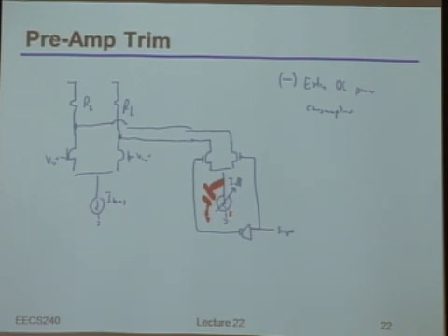Okay, so you said that I've already gained up the offset. It is true I've already gained up the offset. Now, if you think about it, the amount of current I have to spend in this thing is really proportional to this current. Right? Because that offset just goes through the GM of these input devices to become a differential current at the output. So if I want to cancel a certain amount of offset, I basically have to figure out the equivalent current to cancel that same voltage at the input.